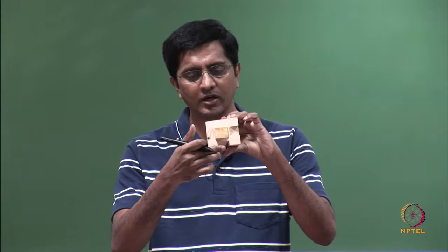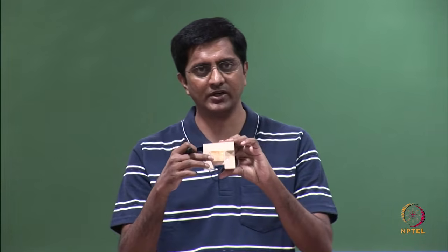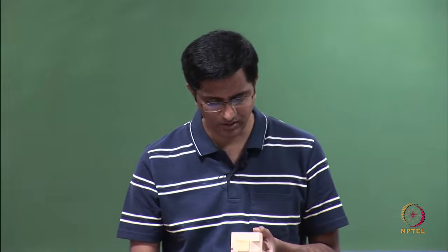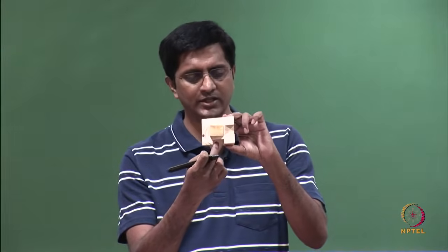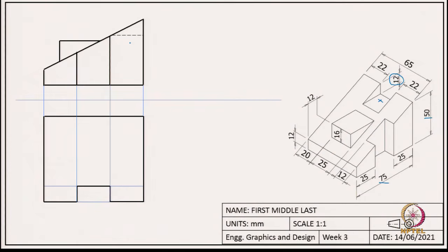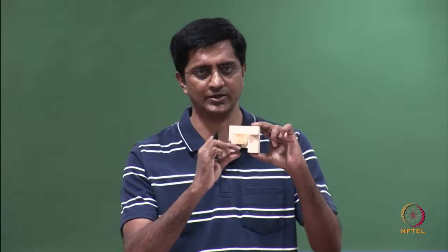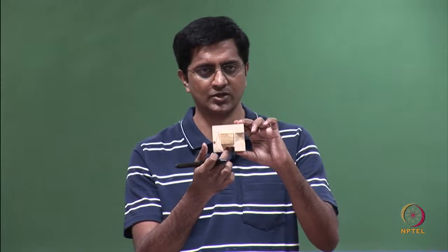So, I can't draw the bottom line because I know here there is a slot. So, that is why I left it without drawing the outline. Okay. Now, let us see what are the other information. So, I will draw few more construction lines or the projection lines, which will help me define this bottom slot. So, after that I draw the outline. So, now I am able to capture this slot because I know what is the height of this slot, which is given as 12 units, and using the projection lines I am able to completely define this slot.